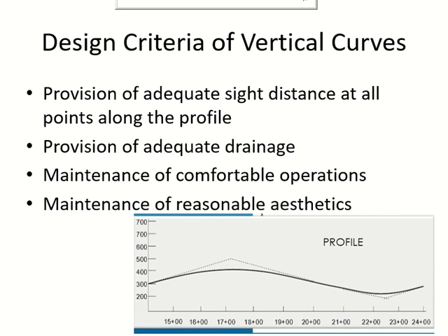Okay, we started talking about geometric design, which means the dimension of the highway. It can be done in the horizontal alignment, vertical alignment, and cross section. Horizontal alignment means you are looking at the road from the top, the plan view. So you see the direction of the road and the changes in direction with the curves. And then we discussed some points which you have to consider for the horizontal alignment.